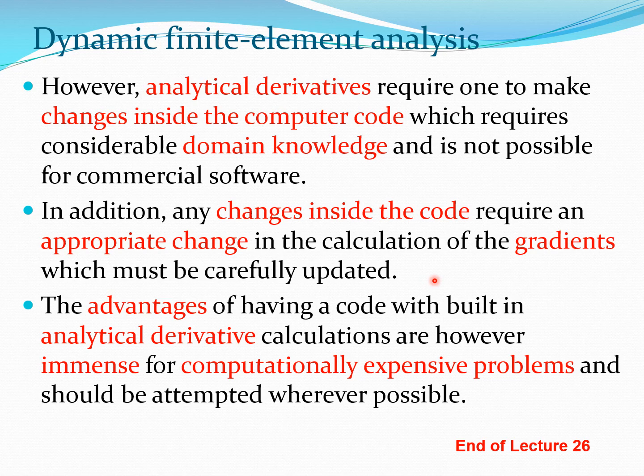But the thing to keep in mind is that if you make any changes inside the code to the formulation part of the problem, for example, if you are calculating the frequencies, you must make appropriate changes in the calculation of the gradients also during that time, or your code will progressively start to diverge in terms of calculation of the objective function and in calculation of the objective function derivative.